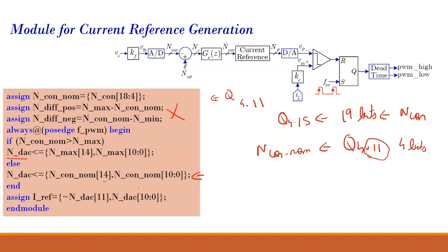So you are getting actually your ndat. ndat became 12 bits, so it becomes Q1.11. And we are inverting the sign actually. This main MSB bit, we are inverting the sign. We're converting this into offset binary.